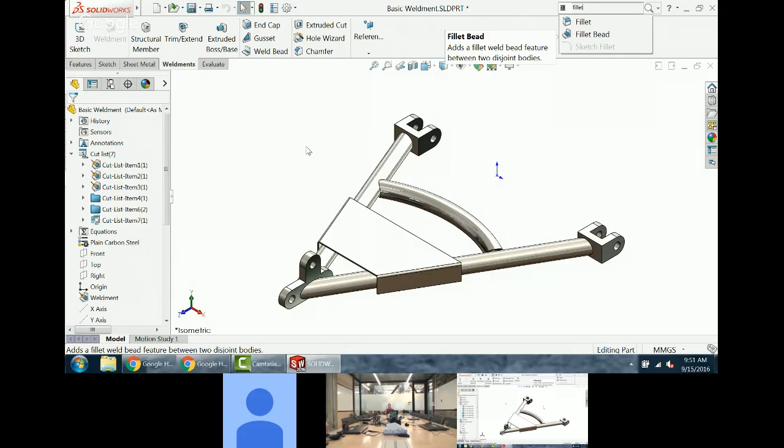If you've got a ton of welds and you're worried, hey, this thing's got to fly in the sky or go into space or whatever we're doing here at X. If weight is a crucial consideration, you may want to put those fillet beads in there. They also help a little bit with analysis because of these gaps that we've got going here. They're not actually touching each other.